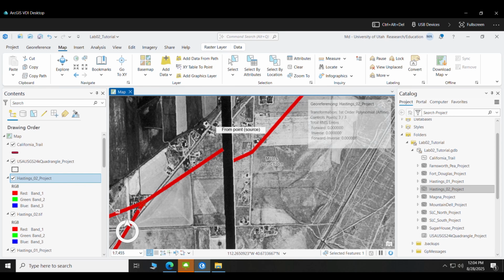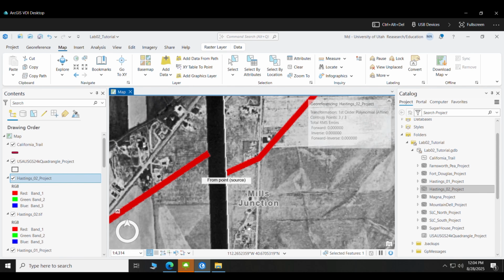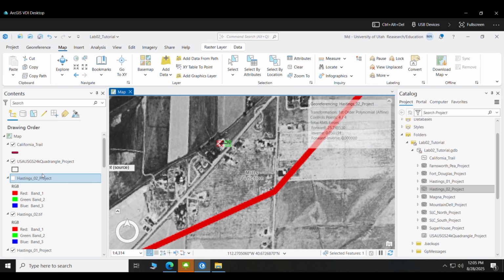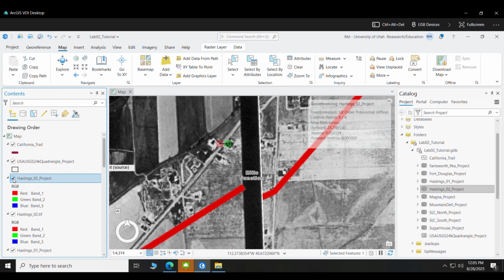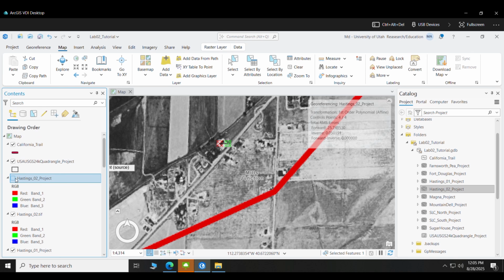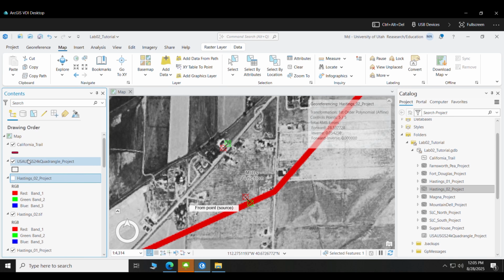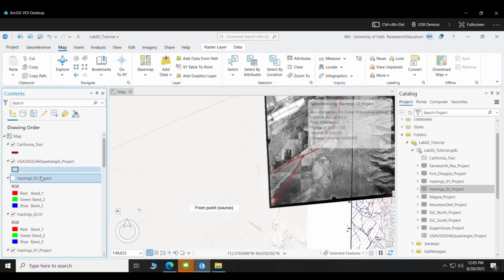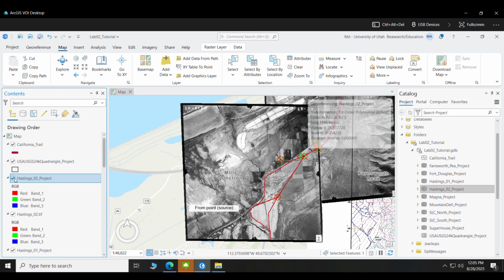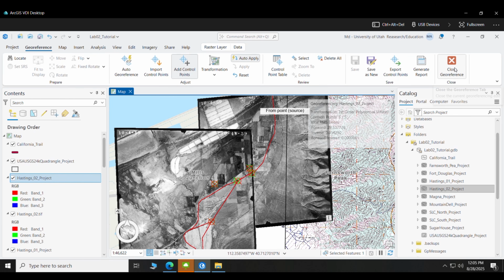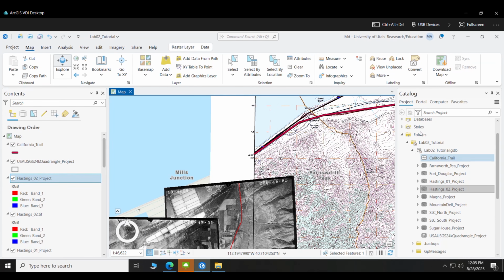As I said, the images have a different coordinate system than the topographic map, and also it is quite difficult to match this 100% perfectly, because these do not have any grid lines present here. So we will try our best to match as much as possible and keep the control points as much separated as possible. We will take those control points quite far from each other. And now I think it's quite good, so I'm saving our georeferenced image.